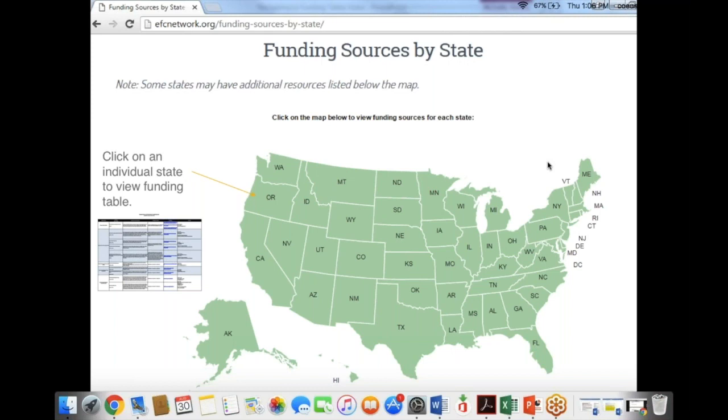And that's okay. What isn't okay is you go out to a piece of equipment and your inventory tells you this is, you know, a 4-inch PVC pipe, and I dig it up, and lo and behold, it's a 6-inch cast iron pipe. Well, that's great that you know that now. So now I know it. Now is the time when I update my inventory, my registry. And so I say it's always right to be wrong the first time.